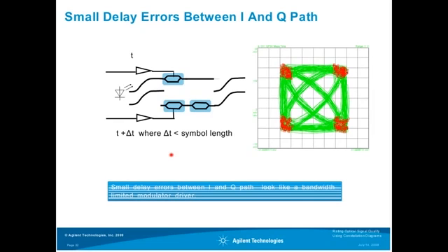We can even think that a delay between these two symbols, between these two transitions, or let me say it in another way, a different bandwidth causes different group delay, and the group delay implies that there is a different traveling time between these two paths, and this indeed is exactly a difference in the symbol positioning of these signals.